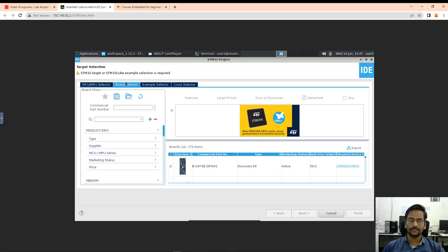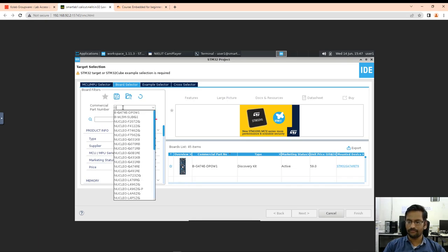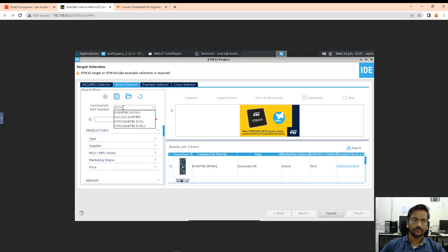We are going to select based upon the board. So go to board selector and try to type the board number. We are using Nucleo G474. So I am typing G474. You can observe it here, Nucleo-G474RE. This is the board which we are going to use.